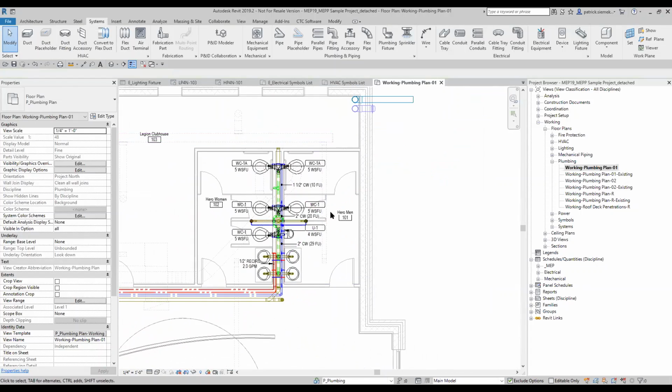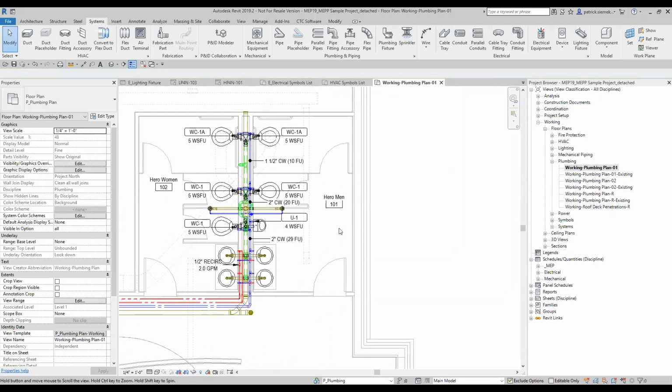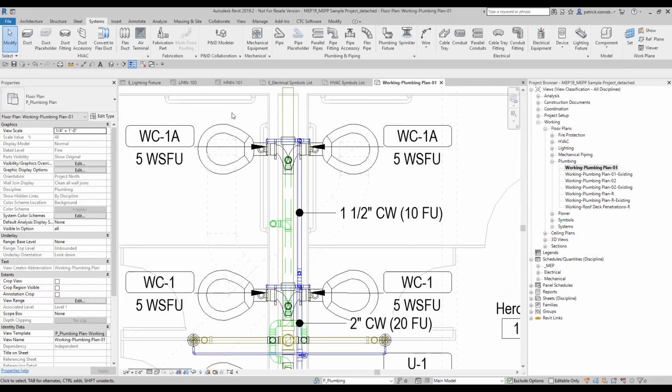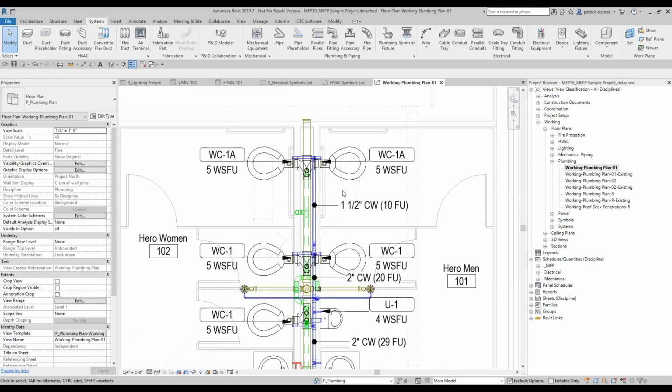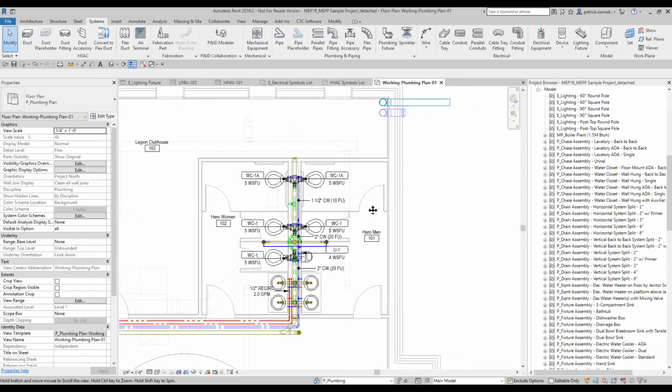Along with these plumbing fixture connections and the families being used, there are already a lot of preset standards. If I have a back-to-back wall-hung plumbing system, instead of recreating all of this piping, inside of the productivity pack there are groups that have been created and developed based on industry standards.